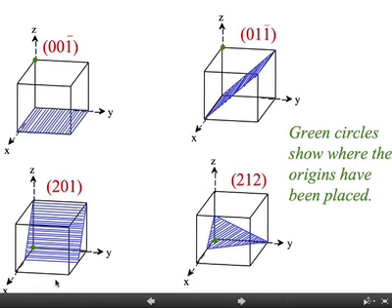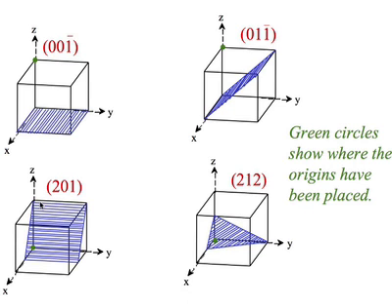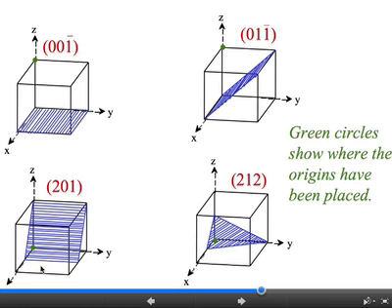That's the y-axis. That's a plane that's parallel to the y-axis. There's no intersection, so it's infinite. Then the third coordinate, the intersection in Z, is 1. I'm assuming it's a unit cube, 1, 1, 1. So we have intersection coordinates at half, infinity, and 1. Then you take the reciprocal of these numbers, so you have 2, 0, 1. Is that clear? That's how you get the Miller indices for this plane.